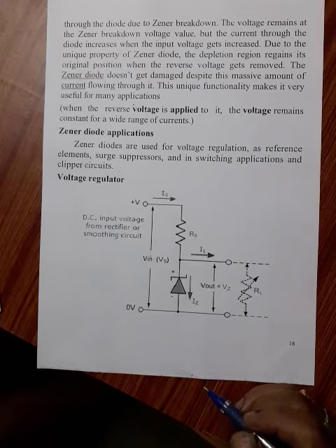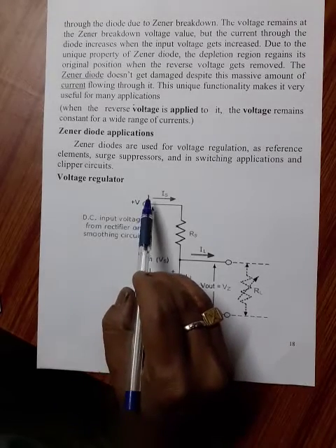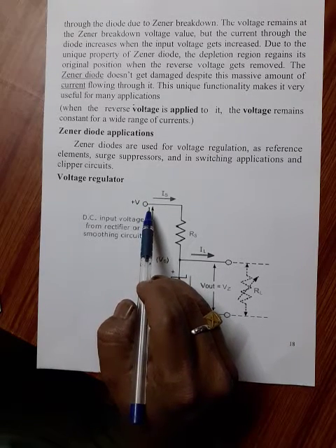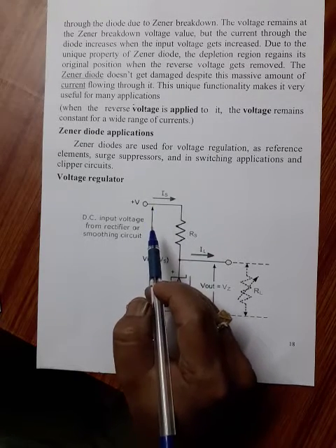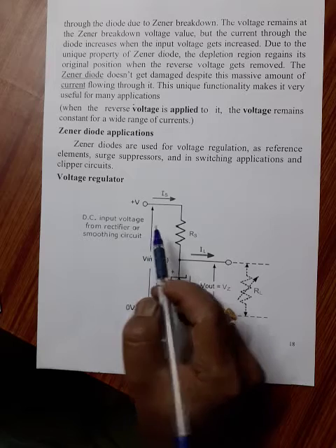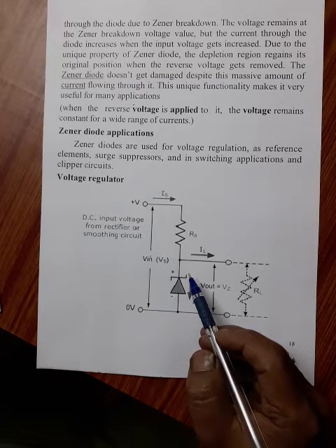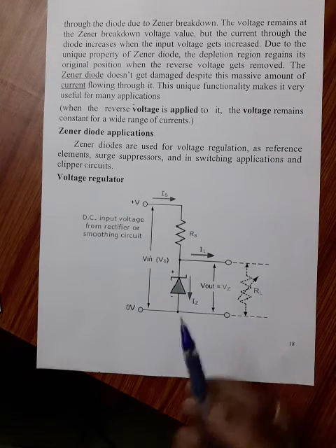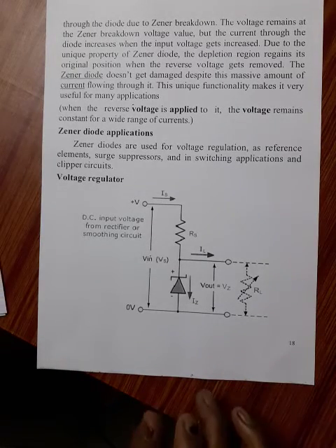The zener diode is connected with its cathode terminal connected to the positive of the DC supply, so it is reverse biased. It will be operating in its breakdown condition. Resistor Rs is selected so as to limit the maximum current flowing through it. With no load connected to the circuit, the load current will be 0 and all the circuit current passing through the zener diode will in turn dissipate its maximum power.